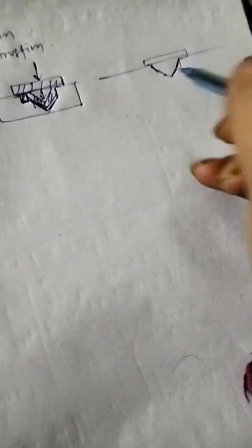In this new diagram, you observe you have a metal stock, and here we apply the pressure. As the pressure is applied, the metal will move to this particular side. Backwardly, the metal moves in the opposite direction of the force applied. In this direction force is applied, but the metal moves in this outward direction. So this is known as backward. The metal moves in the backward direction, opposite to the force applied. This is the backward extrusion process.